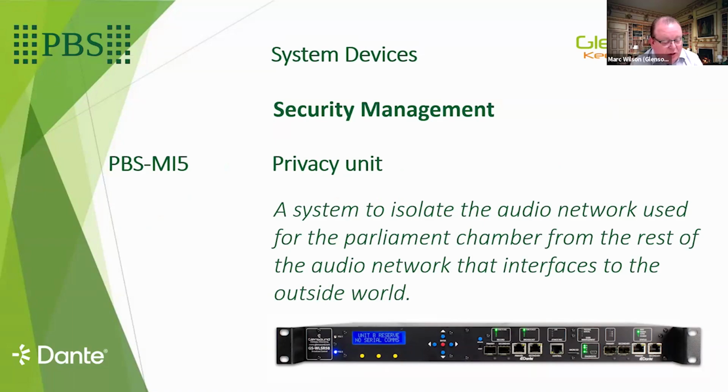This was the original unit that became the Glensound Victoria, if you were interested. So this is a network isolation bridge, where it also isolates the audio network used within the Parliament chamber from the rest of the audio network that connects to the outside world. It means that we can pass audio between Parliament, between broadcast and other users within the wider network, but there is no data connection.